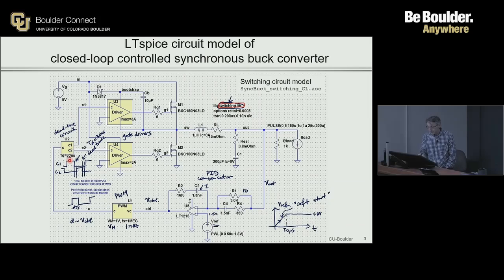So the dead time, again, really, what is the purpose of that time? The purpose of that time is to ensure that we don't have these two devices conducting at the same time. So you really go back from that purpose into how that time decision is made. Okay. So you want to find out really what is the application you're working at. And here, in this case, we have relatively low voltage and high frequency switching. We have fast switching devices M1 and M2.